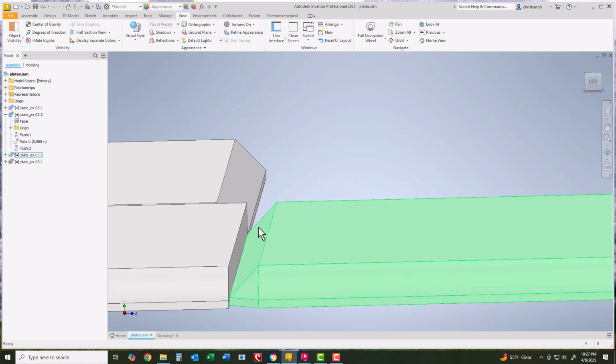I've got the bevel on this plate, and I've got a square surface on this plate, and you're putting these two together. Typically, this would probably be where this would be an existing structure that you're welding to, and you're bringing in this new piece and trying to weld it to this piece. So you bring this in already pre-beveled, and so you've got a bevel groove.